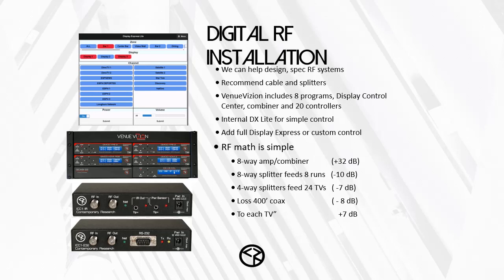And then as you install the controllers, you can actually use that web page on a laptop and go ahead and test the TVs as you install them. So by the time you're done, you know it already works. There aren't any questions. If something doesn't work, you know, okay, it is working. So, did I forget to screw in one connector? Is the power off on the TV? Things like that. So troubleshooting this system becomes very simple.